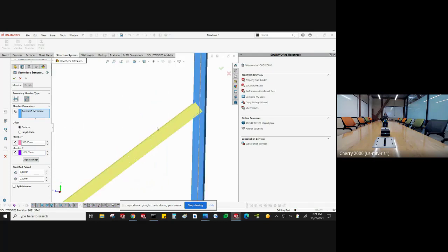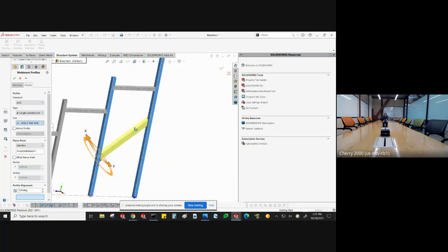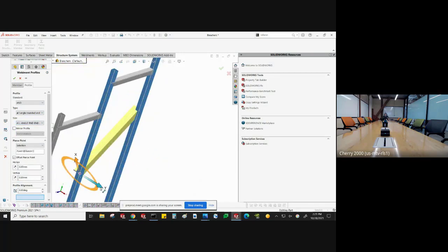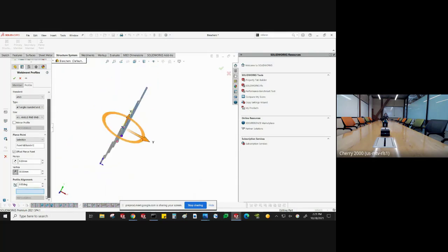Right now, it's defaulting to the same cross-section, but for your secondary cross-section, you can actually use a different cross-section. So if I was going to use something like an angle iron, you see where I put it right in the middle. I do have the ability to either just drag and drop this thing to the position that I want. I can also play along with what angle this comes in at, things like that.